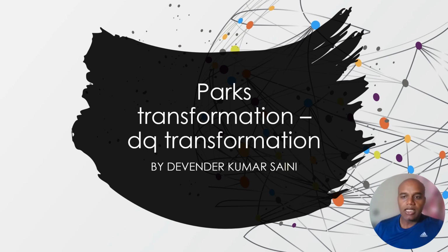Hi everyone. In this video, we will see the Park transformation, also known as the DQ transformation, where DQ stands for the direct and the quadrature axis. As we know, the DQ transformation is very helpful to convert my two phases, which are placed orthogonally, into the DC values.